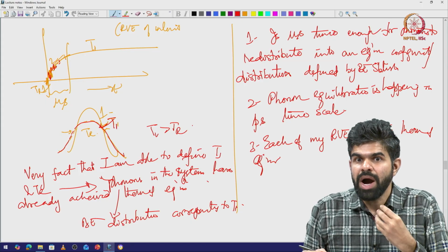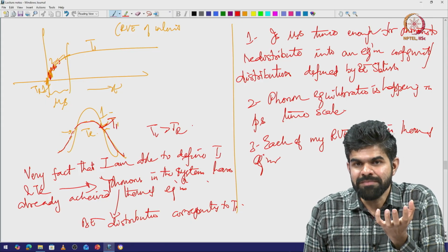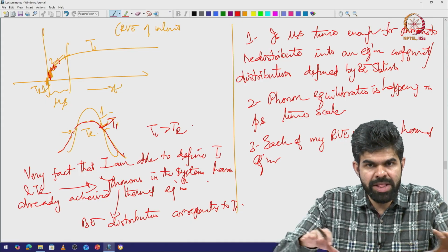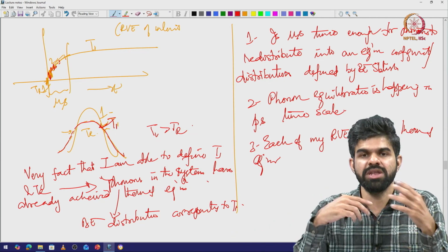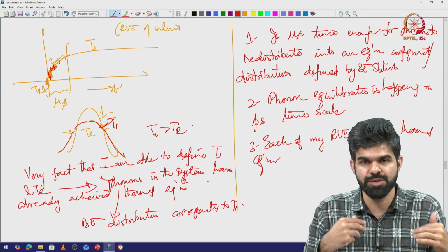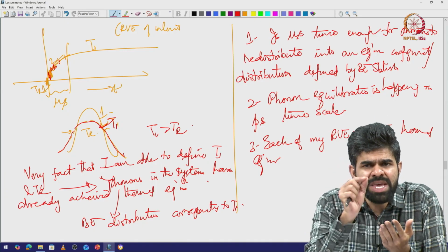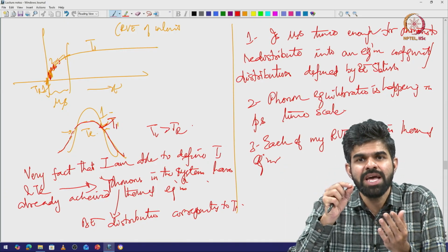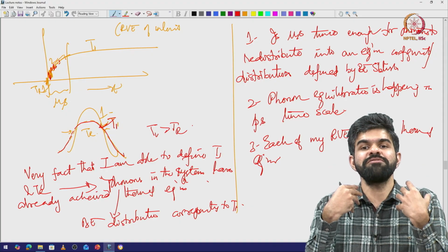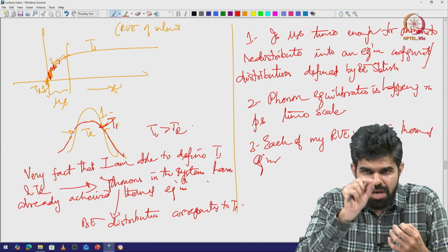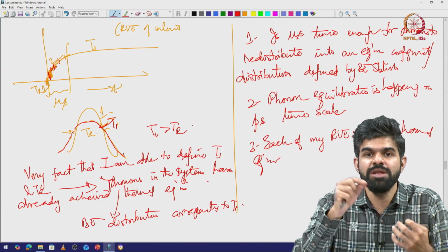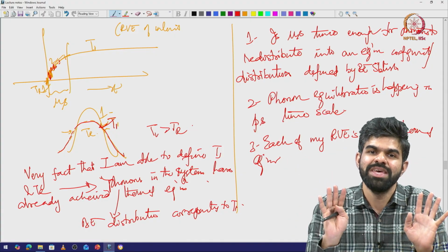So now I am going to define equilibrium, right. Overall there is some heat transport happening. Something is flowing, so this is a non-equilibrium problem from a heat transport perspective. But if I am just looking at every individual piece and thinking of the equilibrium definition from a StatMech perspective, every individual RVE, representative volume element, has already achieved its thermal equilibrium, right.